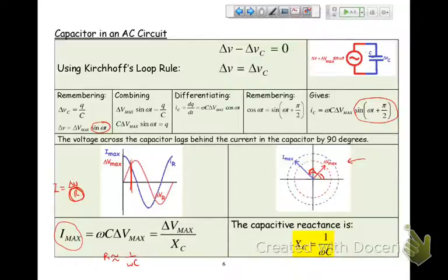And this kills you at low frequencies, because 1 over that means it goes like that. This is omega, and this is my reactance, or my resistance, if you like. And so the capacitor is killing you at low frequencies. So the inductor kills you at high frequencies, the capacitor kills you at low frequencies.